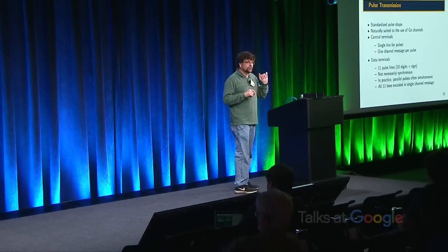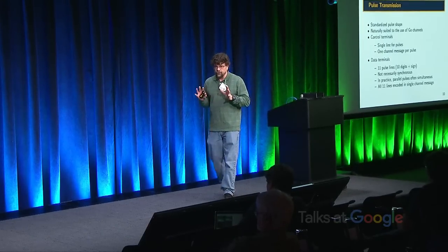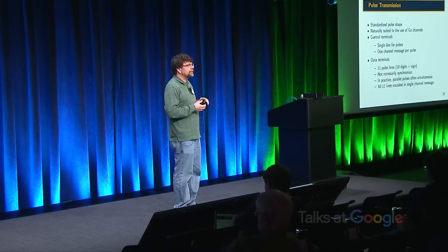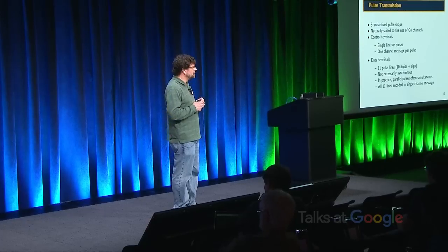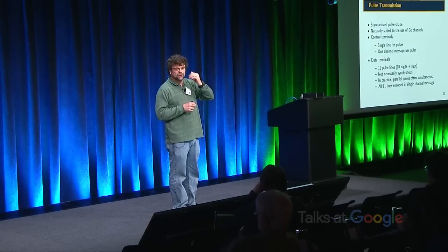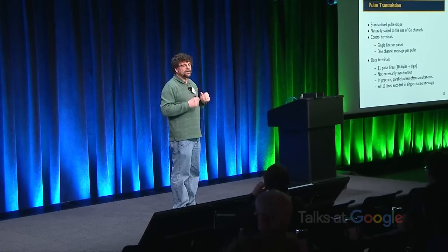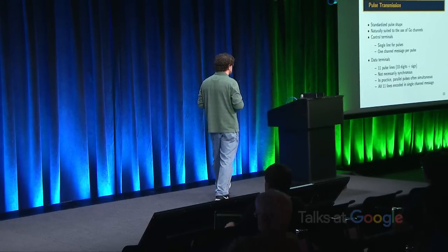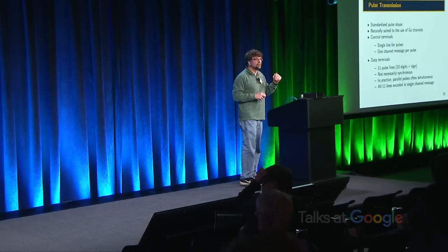Similarly, the clock trunk has 10 or 11 signals. So rather than create the skew that would be involved with sending a different message for each pulse, I basically take the 11 lines and treat them as bits of a word and just transmit an integer. So that becomes the way in which the data transmission is emulated.